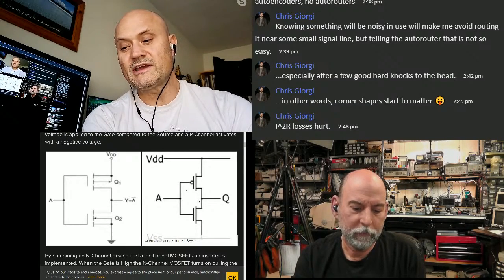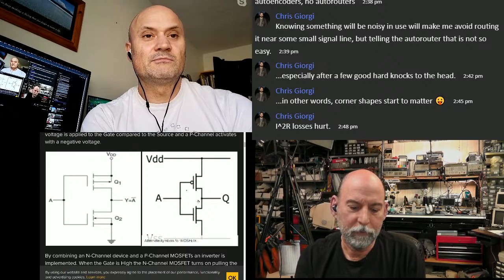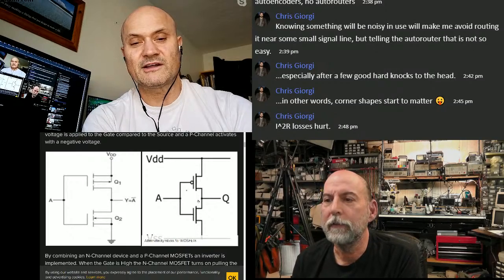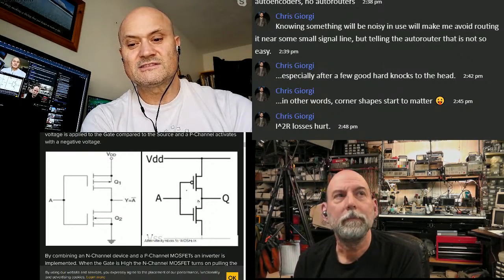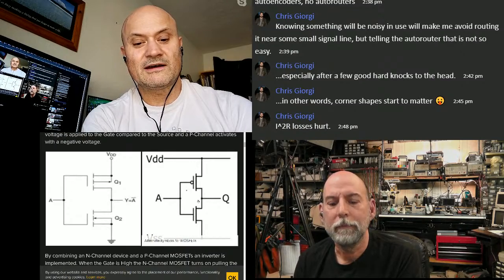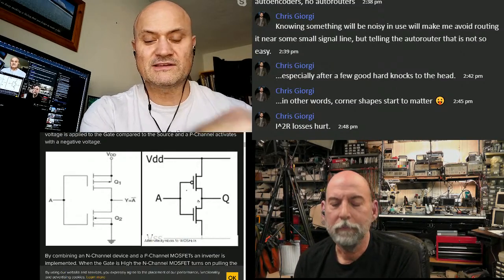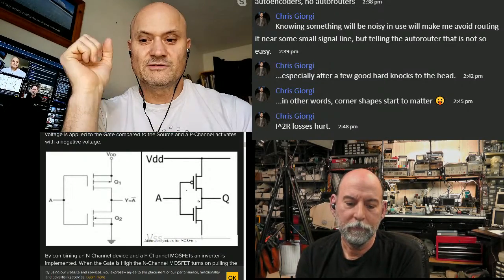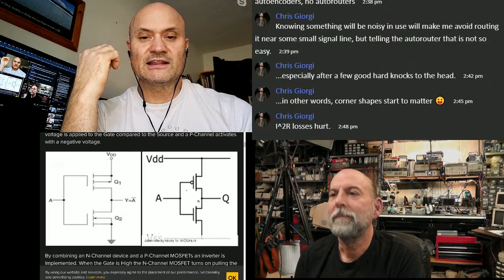And usually you have a high layer count because you have a lot of plain copper in there for grounds and powers and for that kind of current. And that actually increases the stability of the board. What people have trouble with is that all that copper has to be etched to make it adhere to the adjacent dielectrics.